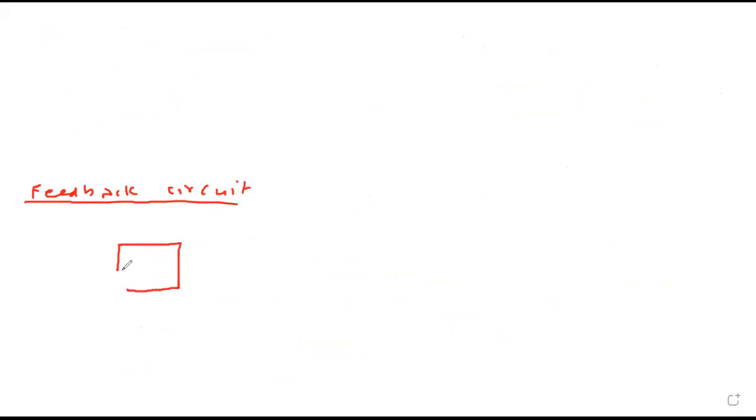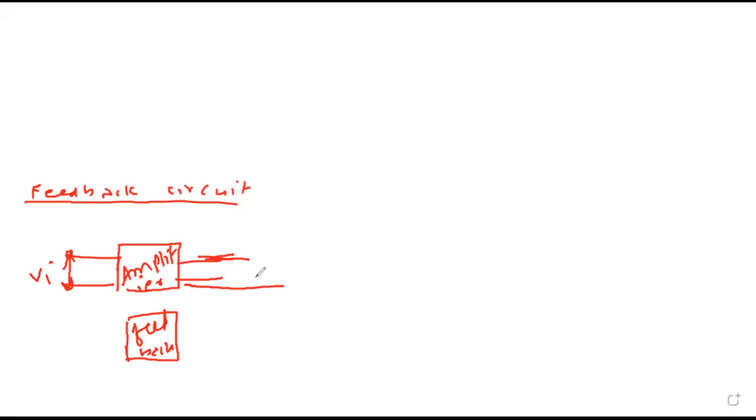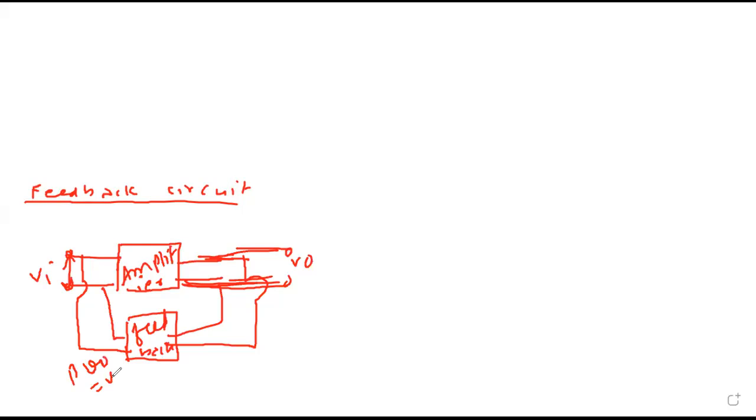Then I'm just drawing block diagram for only feedback, positive feedback, negative feedback, then obtaining condition for sustained oscillation. So first here feedback or just oscillator. It consists of two units. One is called as amplifier. Second is feedback circuit. From here we give input, and then from this output we take input back. So this is called as feedback. So here part of output voltage is obtained as feedback here.